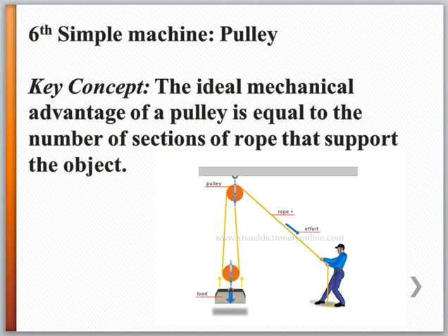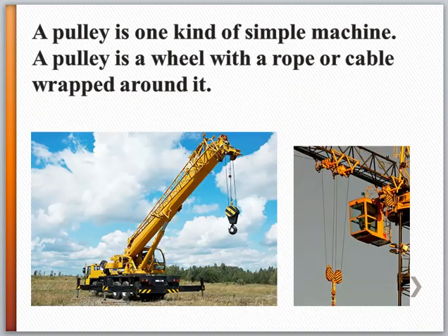And then finally is the sixth type of machine, and that's a pulley. Again, I'd like to have some videos later to show you some of these simple machines. You can get mechanical advantage with a pulley. Now, if you only have one pulley, the tension in this rope is going to be the same as the tension in that. But if you have a double pulley system, you can actually halve the load or double the amount of force that you can exert with a pulley.